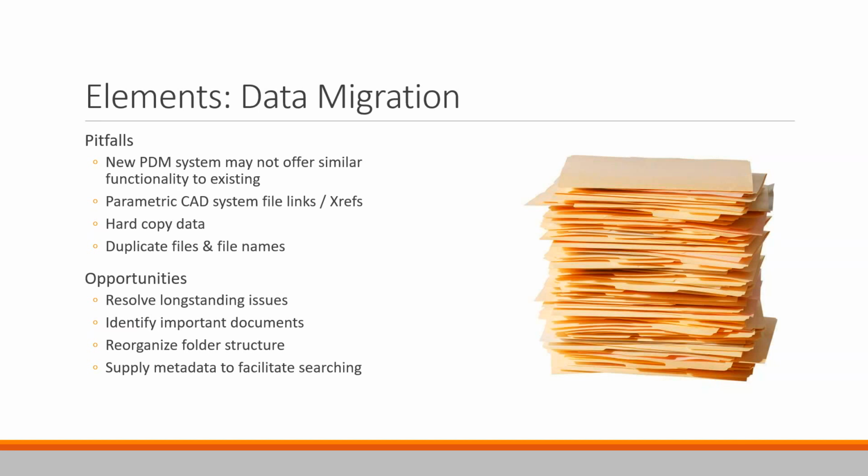So across my whole data set, I may have 20 files called bracket and they're all physically different. If you're very careful with your Inventor data in Windows folders, it doesn't cause a problem. As soon as you start to move files around in Windows folders, that's going to cause a huge problem unless you're very carefully using project files. When you move to something like Vault, a best practice is to have a single project file with all of the data in one workspace.